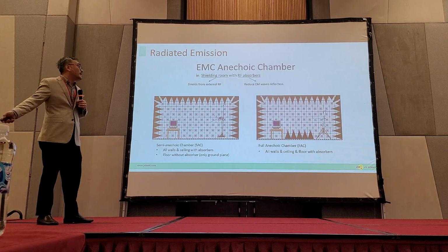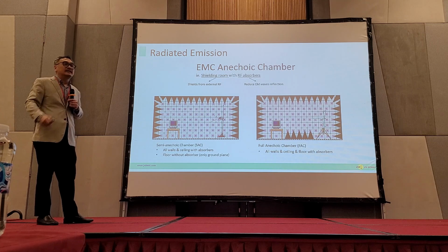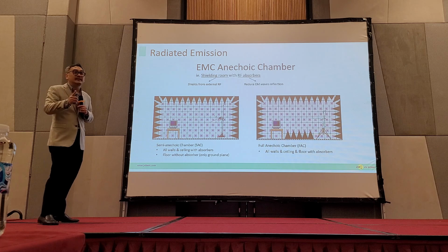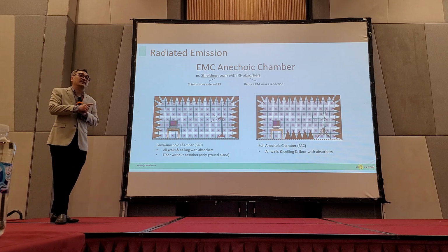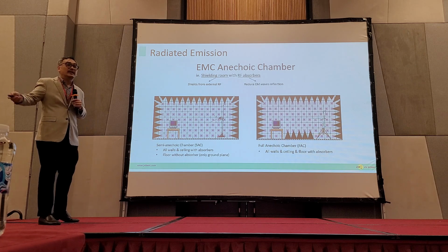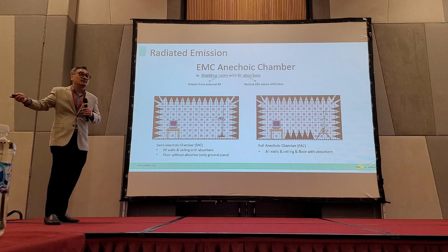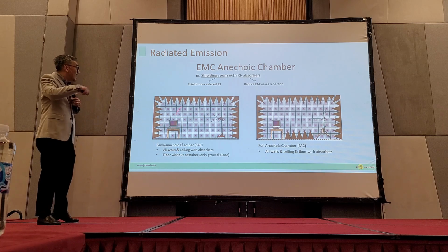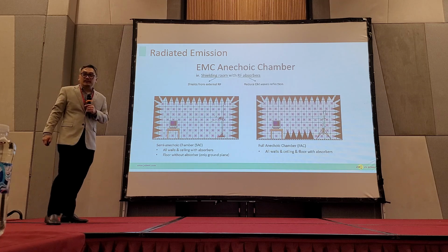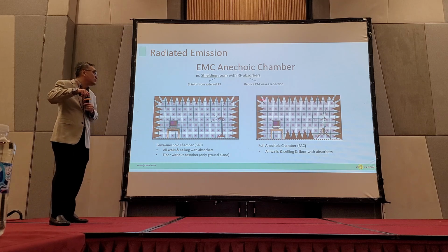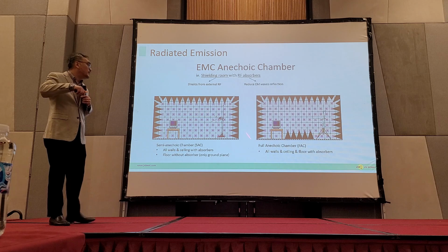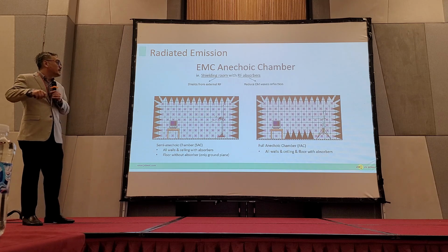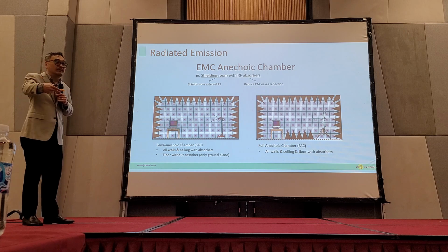That is why now in all EMC setups, I will say 99%, we still have 1% that people do open area test site. But if it is raining, like now it's raining, you cannot do it. You are just in the office, doing nothing. You cannot do measurement. Now they built an anechoic chamber. Either you build a semi-anechoic chamber or a full anechoic chamber, depending on your application. Then you do the measurement inside the building.